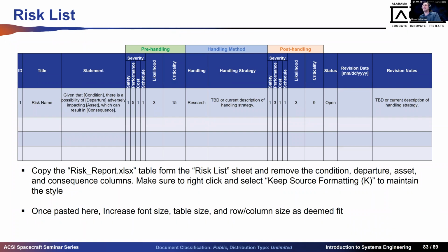You can see that this is a function of our design. We have decided to use a power transistor to operate a heater. The proton strike can impact that heater, causing a single event effect like a single event gate rupture or single event dielectric rupture. And that can result in a loss of electric power to the heater.